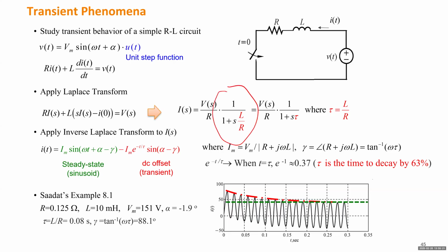So for this case, the voltage will have an instantaneous change, and then we'll call it a delayed change on the current. That delay can be modeled by a first order system with some time constant. Then we move to the equivalent circuit of the generator. When we open the circuit, the current has an instantaneous change and the flux has a delayed change. We just figure out what that delay is. That will give us some time constant. If that time constant falls into the sub-transient dynamic, it will be called a sub-transient parameter. If it falls into the transient dynamic, it will be called a transient parameter.